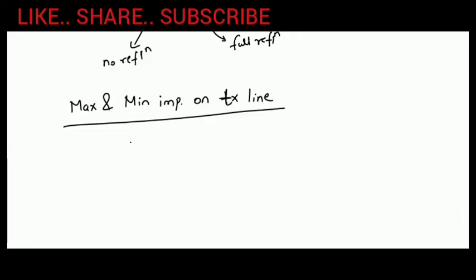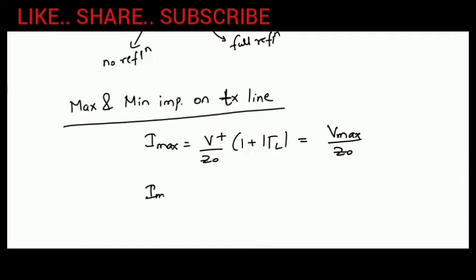Imax is V plus divided by Z naught into 1 plus mod of tau L, which is Vmax divided by Z naught, and Imin is Vmin divided by Z naught.